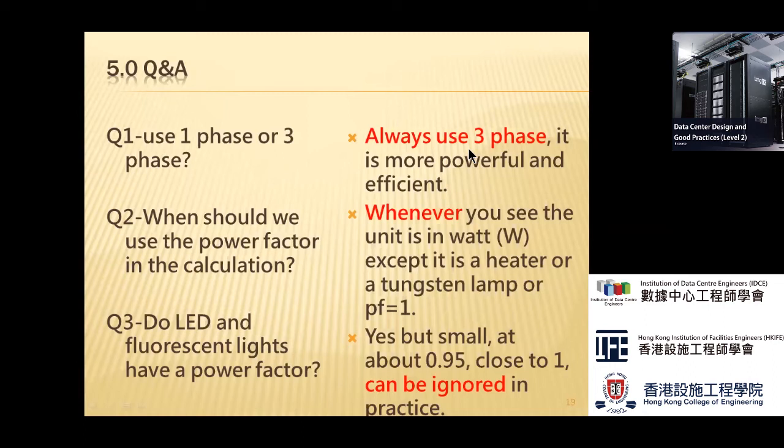However, you find that for fluorescent lights, for lighting, you have to multiply by 1.8 in general. But for the power factor, because it's a heat resistant type of fittings, its power factor is usually very high, 0.95 or close to 1. And therefore, the power factor can be ignored. But if you want to do a more detailed calculation, yes, take the wattage and the power factor into account.